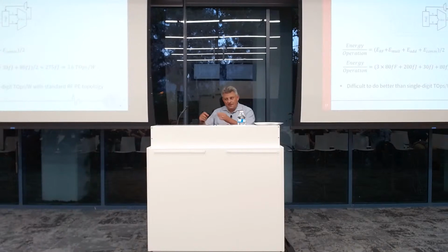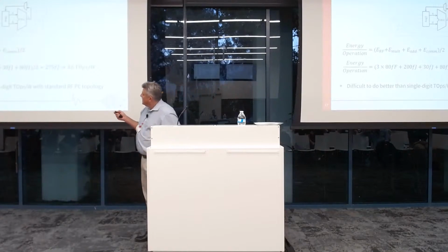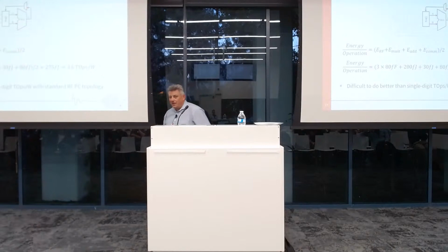So if I go into these tiny tiles that have a register file and a multiplier and an adder, that's actually what it looks like. So you have some ALU and then this register file, and you have to fetch operand A, operand B, and then you do a multiply, and then you have to write back the result and so on.